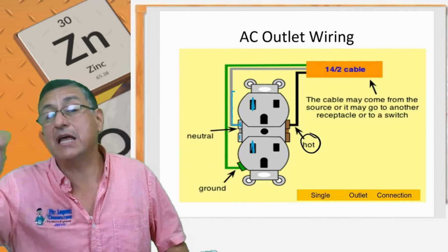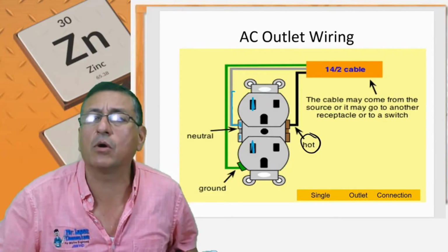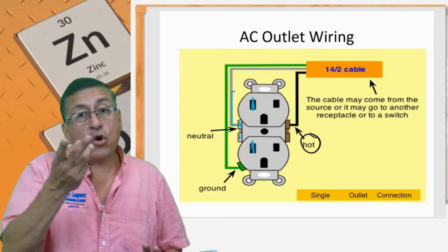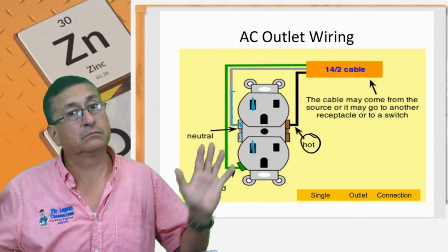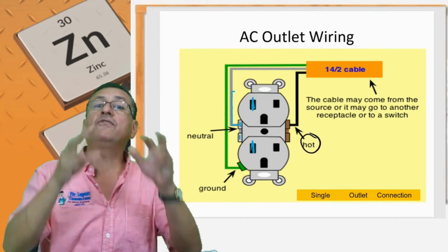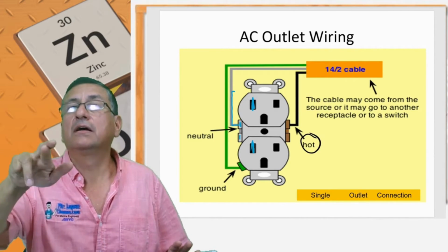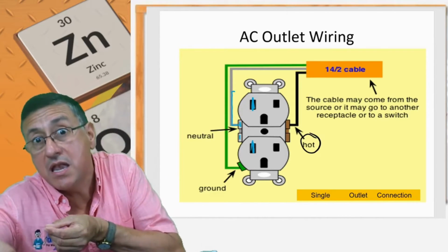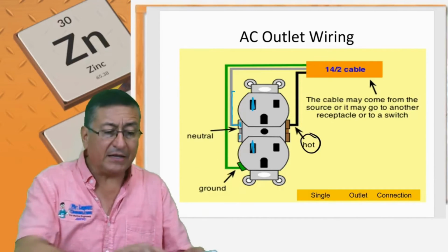You have that constant amount of current, 2 amps, 3 amps, 5 amps, moving through the bonding system constantly, 24 hours. This is catastrophic. Once again, you have two chances. A wrong connection on the panel, the hot enters into the neutral and the neutral into the hot. This is one possibility. Other possibility is outlets improperly wired. If you have outlets improperly wired, you have returns improperly connected, and you have at the end of the day the bonding with current. Remember this picture.